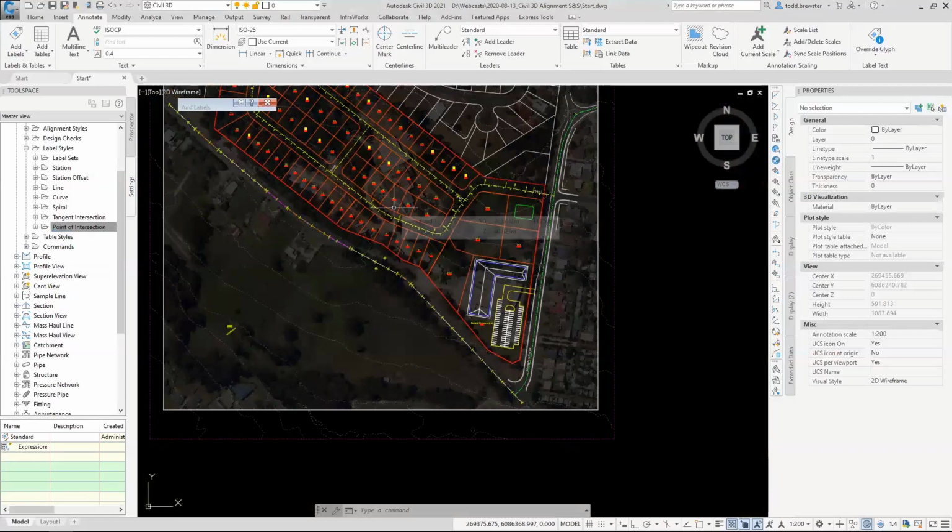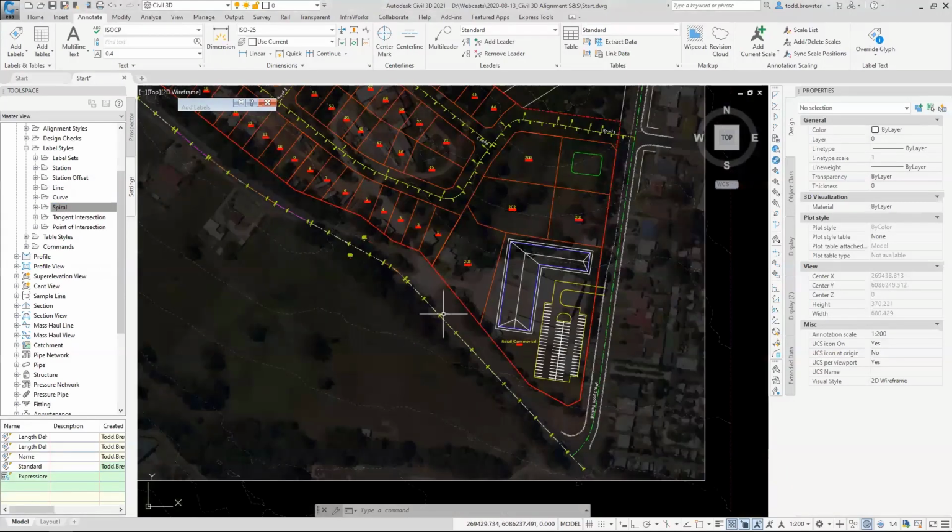The segment labels are these four here. So it is line, curve, and spiral. So they are the three possible parts that you get for your alignment. And you can label their geometry up in terms of maybe bearing and length and stuff like that. And you can label the alignment with those.